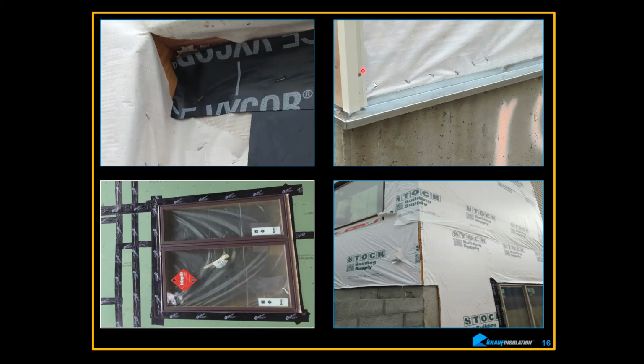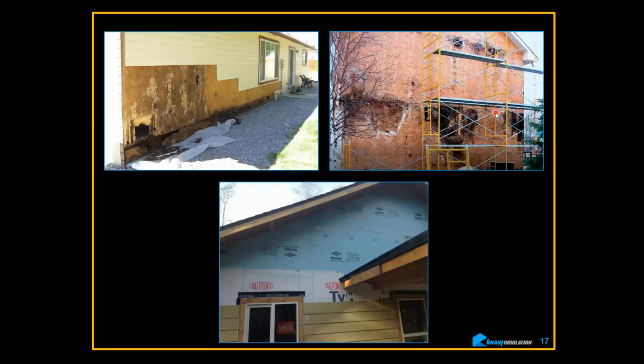And this will do no good because it will go right into the plate. I guarantee you there's no sill seal on the inside, no sealant on top of the gap where the sill seal is, not only on the inside, but I can guarantee it's not on the outside. And this water is just going to run down any little capillary crevice that they can find along this, and it's going to get right into the building. And 10 years down the road, they're going to be replacing wall systems. So you need to pay attention to that.